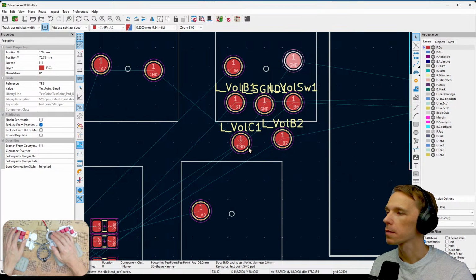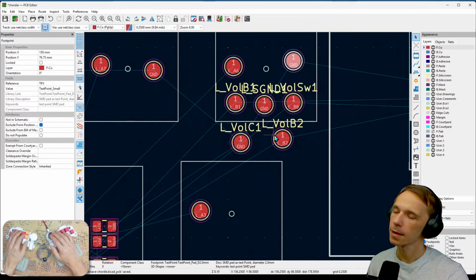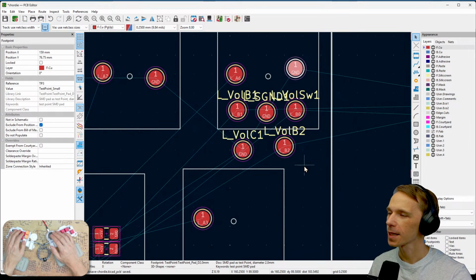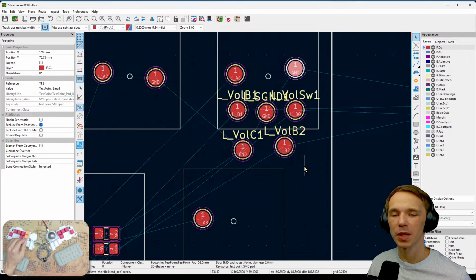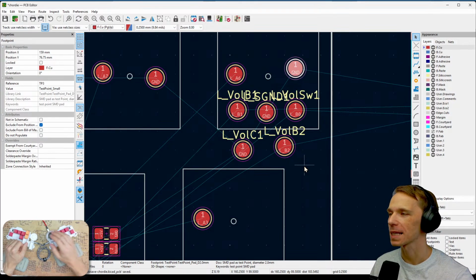Well, actually over here, okay. I was thinking that since we have a common pin and ground pin, it's gonna be the same. It's gonna be ground anyway. So I was thinking maybe we can just cut one path and that would be good. But then I remembered that it's gonna be close to impossible to solder two wires to one path. So it's gonna be better to have two.